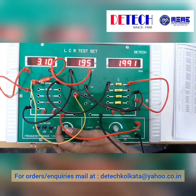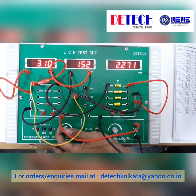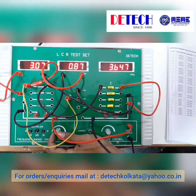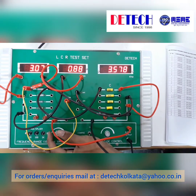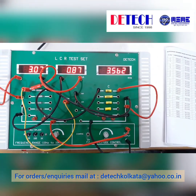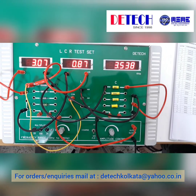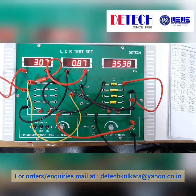Still decreasing. We are increasing the frequency. The input voltage is almost constant. So it started to increase, so we'll go back and find out the value where it is minimum. So this is our minimum value, 0.87 milliampere, which corresponds to the resonant frequency 3.5 kilohertz. So this is our resonant frequency.